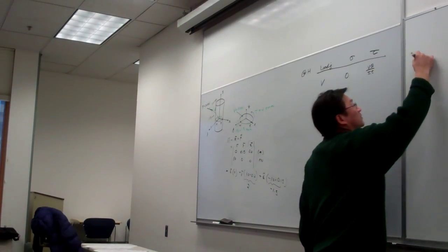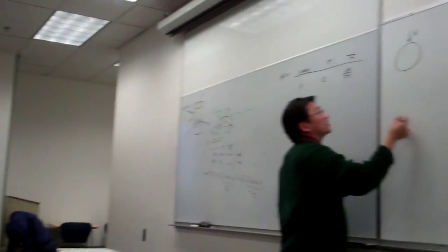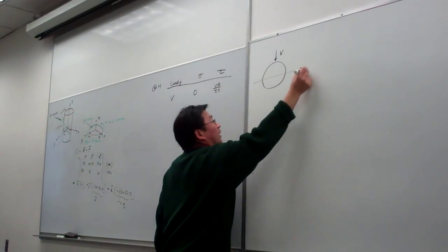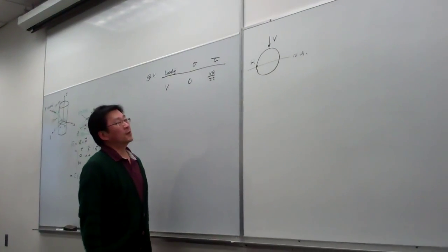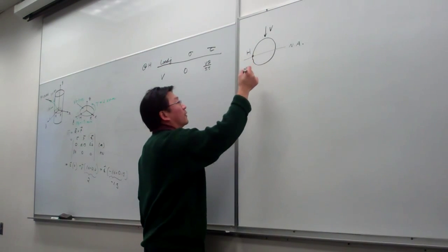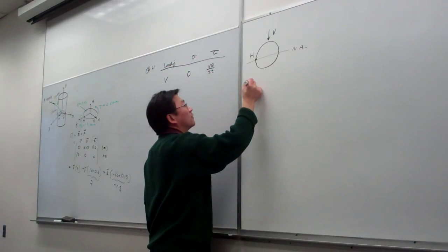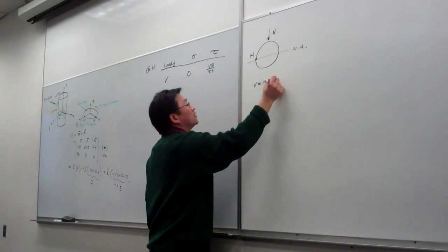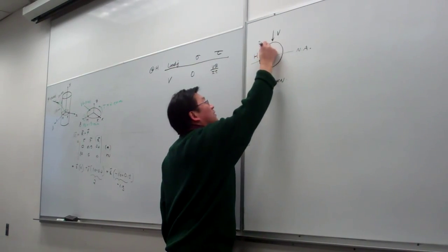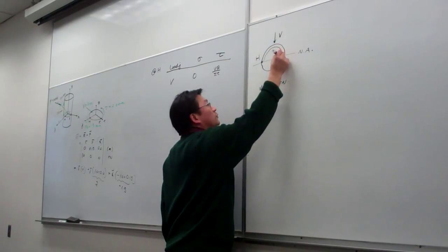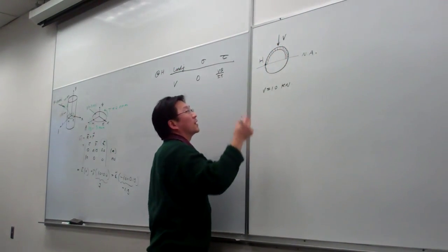And for this case, we can see this is a cross section, and V is applied to here. So this is our neutral axis, and point H is here. Okay, so from here you can see we have to calculate the VQ over IT. So now V is equal to 10 kilonewtons. And what is Q? For this case, this is the hollow shaft or hollow tube. So here that is the cross section we've been focusing on.